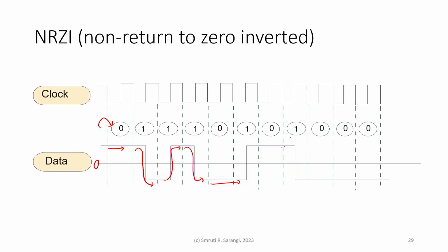I mean, it does more. You will find that in my undergraduate computer architecture book, but this is the base. What is the advantage of doing this? The advantage is that this is synchronized with the clock. It is easier to retrieve the signal because you can align yourself with these transition boundaries.